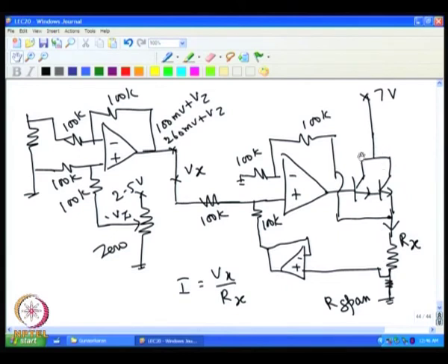Total means this current plus all the rest of the current put together should not take more than 4 milliampere, maybe about a milliampere can be taken. That means at this voltage level we need 1 milliampere, and at this voltage level we need around 17 milliampere, assuming 3 milliampere is drawn by other circuits.